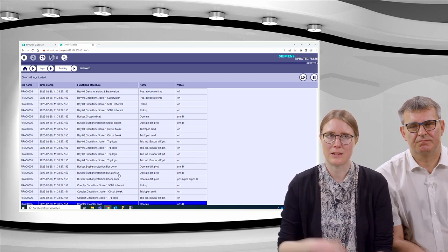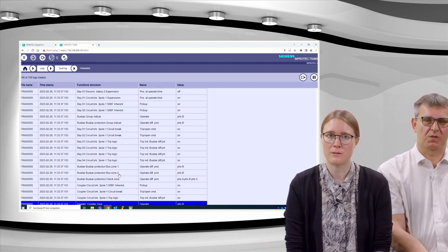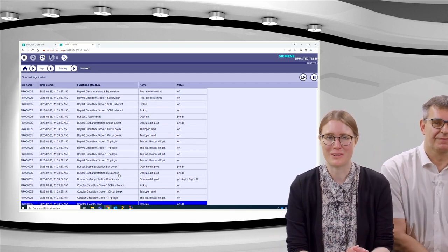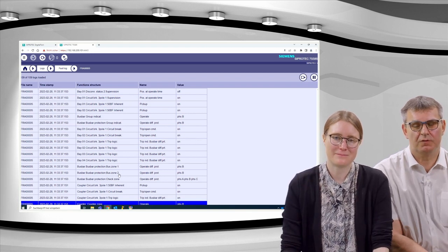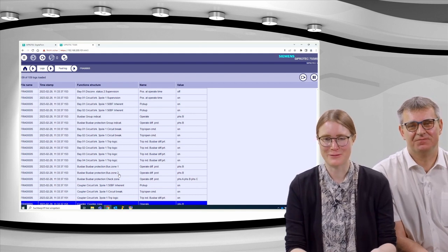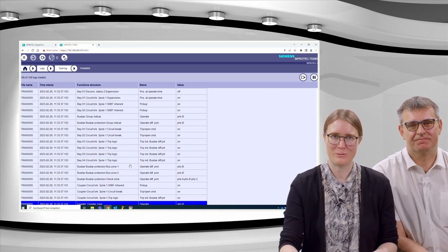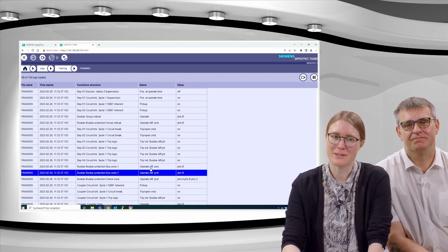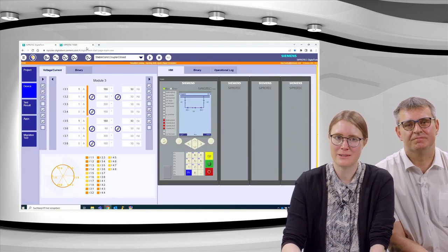And that means as soon as we have exceeded these 5 amps, then we will also get to overlapping mode for 1-pole faults. But in between, so for currents smaller than 5 amps and 1-pole fault, of course, there will be a selective tripping with the end-fault protection involved. But the first test scenario was a 3-pole fault, and this is why we see here this operate for both bus zones. And let's demonstrate the second scenario.